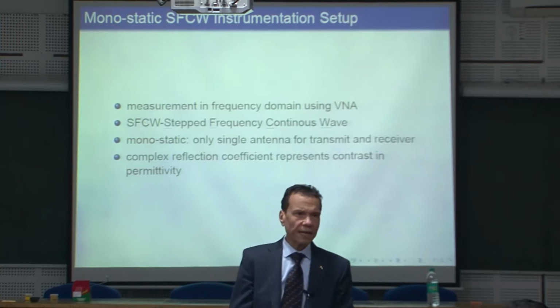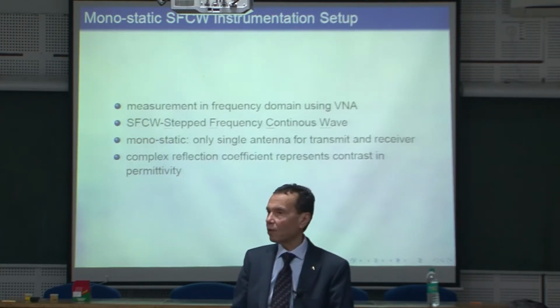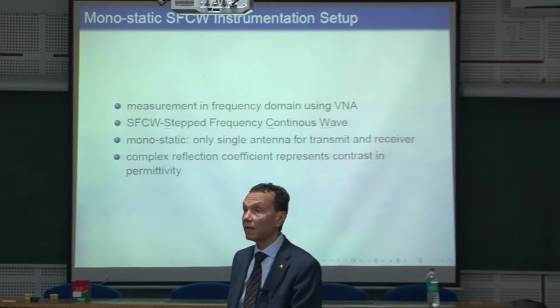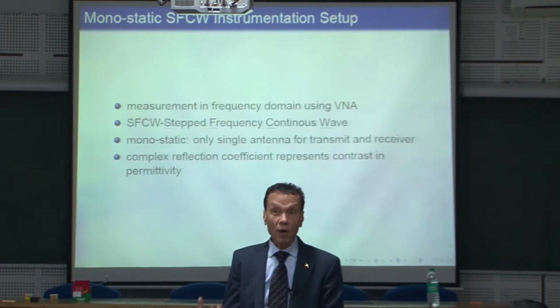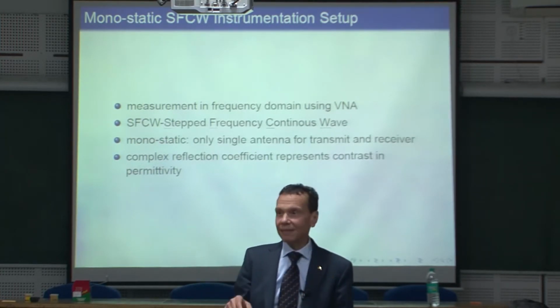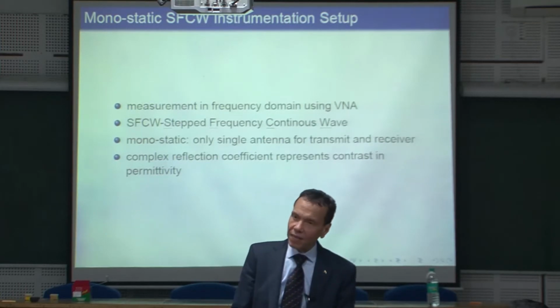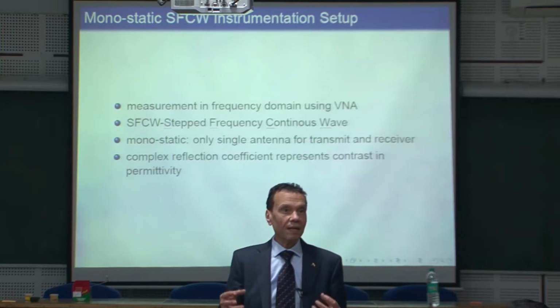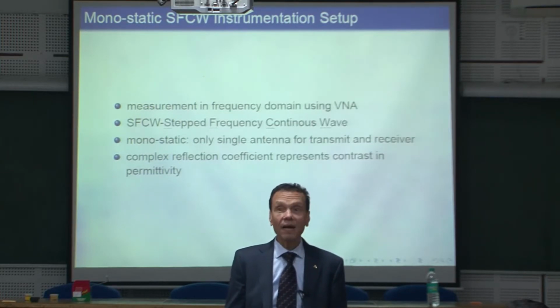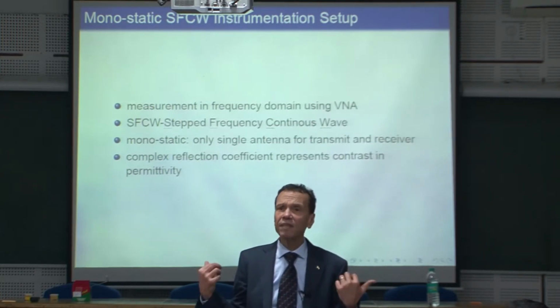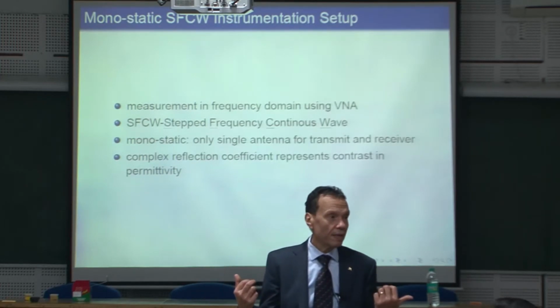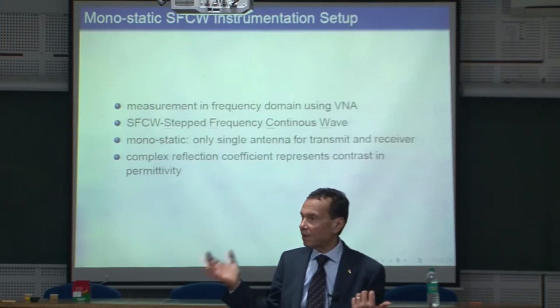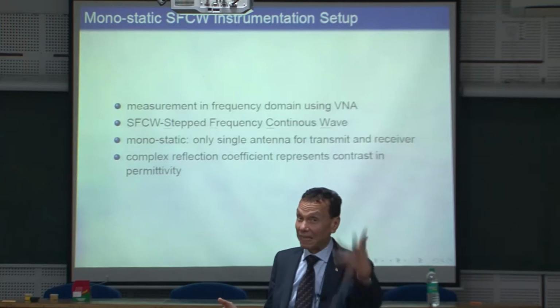And you know from the Fourier relations, the amount of power in the frequency domain is the same as the amount of power in the time domain. So actually, you created very quietly, you don't need to be in a hurry, a very nice signal with a high signal to noise ratio. And the stepped frequency continuous wave is therefore preferable to exciting by a pulse.